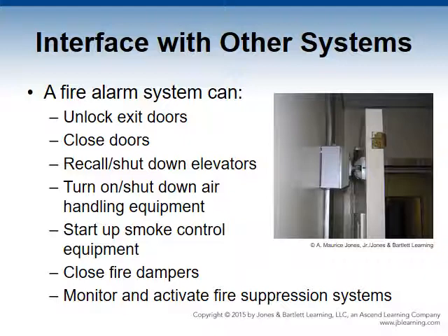Widespread propagation of smoke and hot gases can be prevented by shutting down the system. Startup smoke control and management equipment. It interfaces with the fire alarm system for automatic startup of pressurized systems and other smoke removal equipment. They provide tenable environments that are critical to ensure the building occupants are able to exit safely.